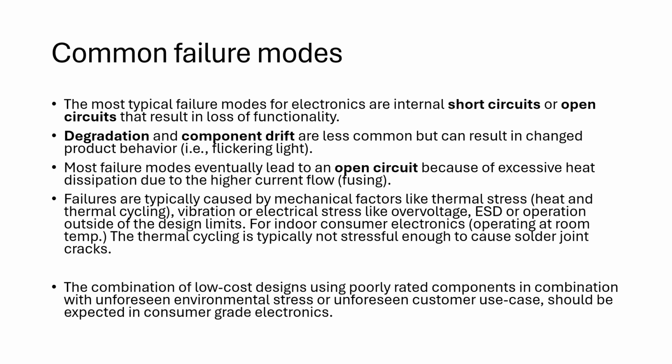I would say it's the combination of low-cost designs in consumer electronics with poorly rated components and maybe unforeseen customer use cases, or that the LED driver in this case is placed so the power dissipation is difficult. You simply cannot get the heat out. This can cause premature failures in these devices.